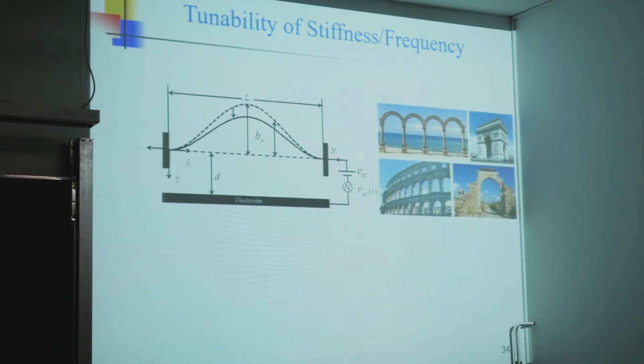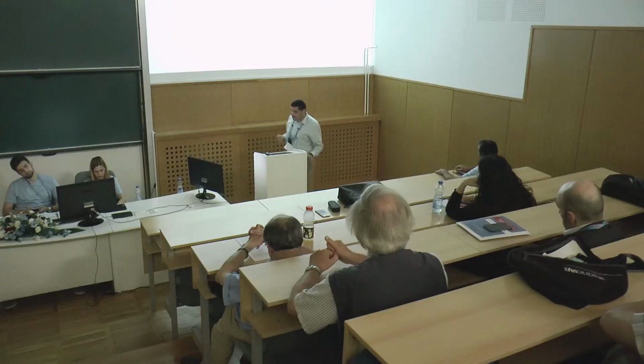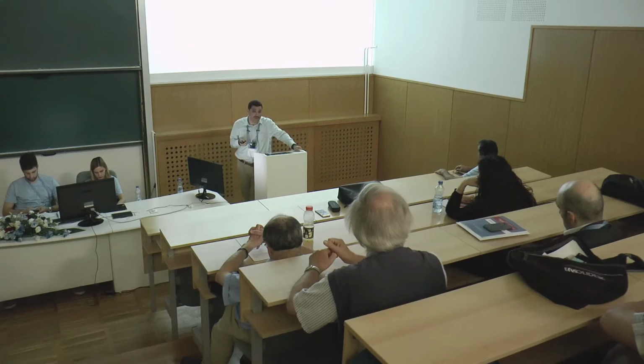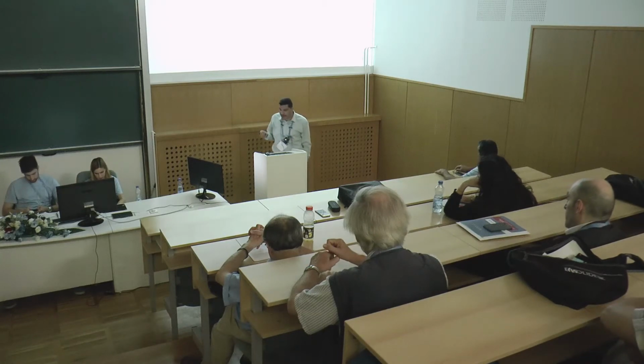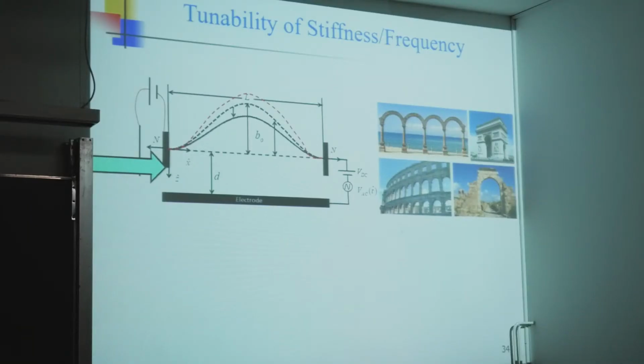Now, there is a concept that I want to introduce in the arch. Something good about it is that it's very tunable. You can tune the linear stiffness of an arch. The more curvature you have, the higher stiffness you get. And that simple concept is the reason why people in Rome and so on used arches for buildings, because they have higher stiffness. So if I can actively change the curvature of the structure, then I can push it and realize higher curvature and get higher stiffness, linearly speaking.